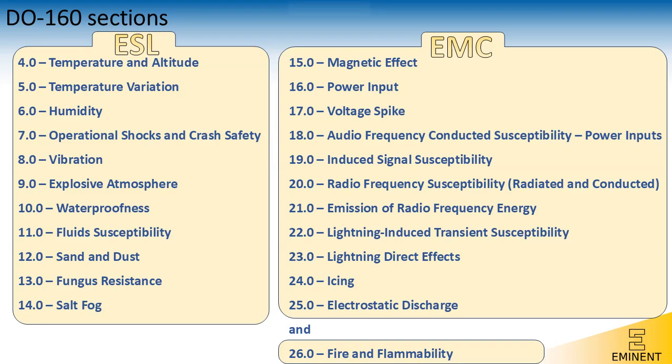durability. Testing phase: during testing, aerospace manufacturers subject equipment to conditions specified in DO-160 sections relevant to the equipment's operating environment. For example, external components like pitot tubes undergo rigorous waterproofness and icing tests to confirm they function reliably in extreme weather.